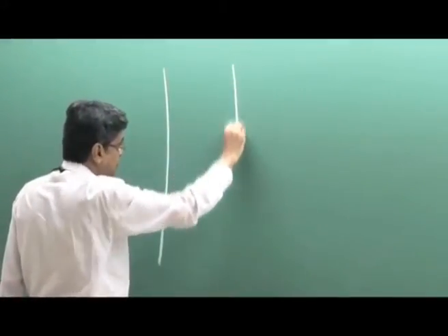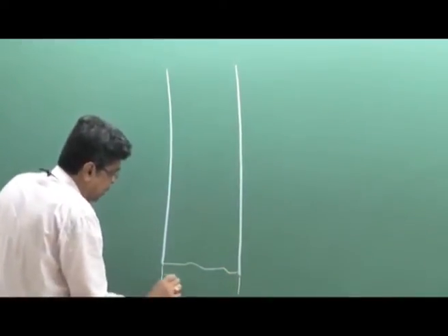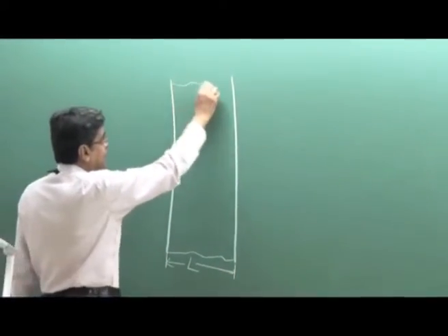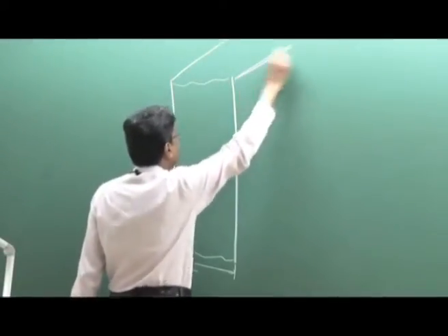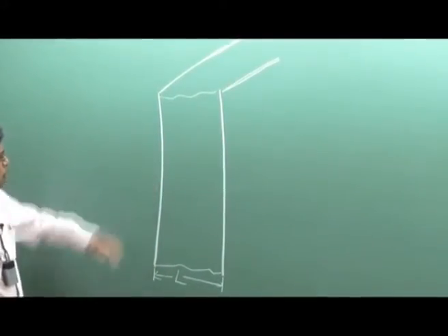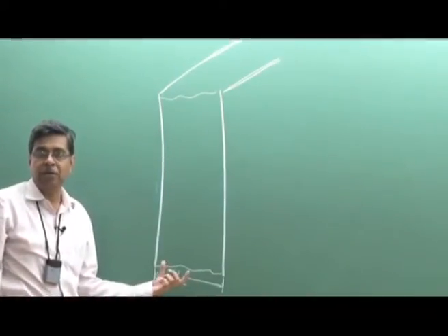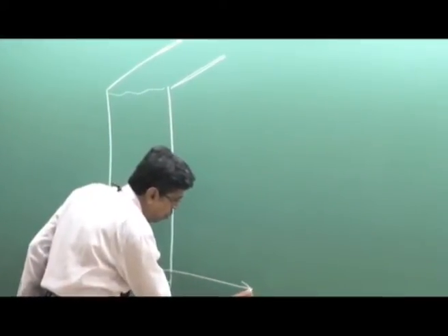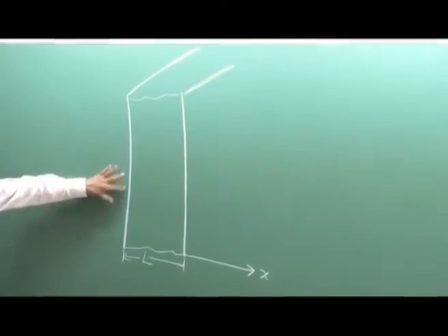Again a plane wall whose width is L, while the dimensions in the other directions, that means perpendicular to the plane of the board and this height, are much higher than this dimension, so that we can consider the temperature to be a function of one coordinate, x, and the problem is specified like this.